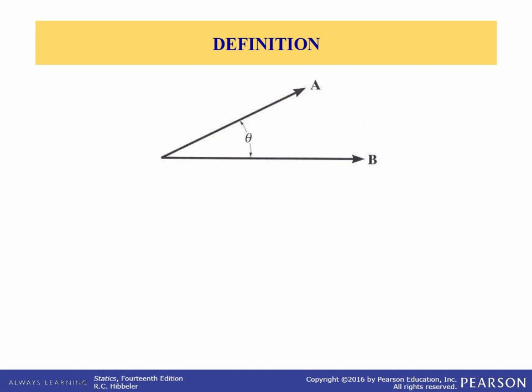Okay, occasionally in statics, one has to find the angle between two lines or the components of a force parallel or perpendicular to a line. In 2 dimensions, these problems can be readily solved by using trigonometry, since the geometry is easy to visualize. But in 3 dimensions, this is often difficult, and consequently vector methods should be employed for the solution. The dot product, which defines a particular method for multiplying two vectors, can be used to solve the above-mentioned problems.